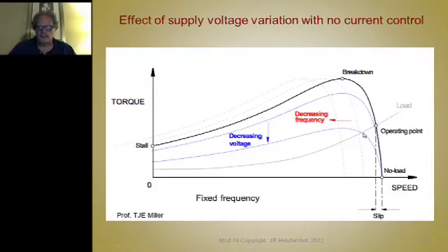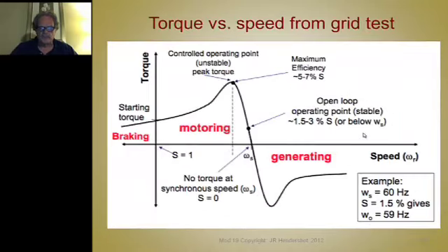But with an inverter control, you can control both of these. So as we'll see, we're going to define an envelope that a machine and an inverter together will run with. And I've shown this plot before. This is the same thing in the motoring area and the generating mode, where some prime mover spins the rotor faster than synchronous speed up to a maximum amount, and so you get generated power at the leads.